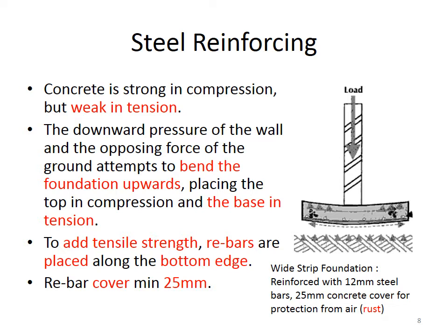Placing the top in compression and the base in tension, being torn apart. To add tensile strength, rebars, which is a common name for reinforced bars, are placed along the bottom edge. So we can see in the image there the rebars down the bottom, wide strip foundation reinforced with 12mm steel